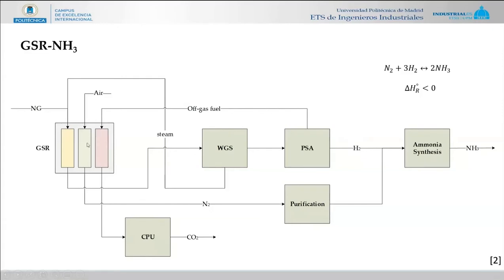Bear in mind that there is some mixing of nitrogen here. And this concept allows inherent carbon capture and storage for an ammonia concept. And finally, we need our nitrogen stream. Again, we have an air stream to oxidize the oxygen carrier. And the nitrogen is easy, at pressurized conditions, it's easily purified to provide the stoichiometric amount of nitrogen for the synthesis. Right? So these are novel advanced concepts for chemical commodities production, in the understanding that they may become potential energy vectors of the future.